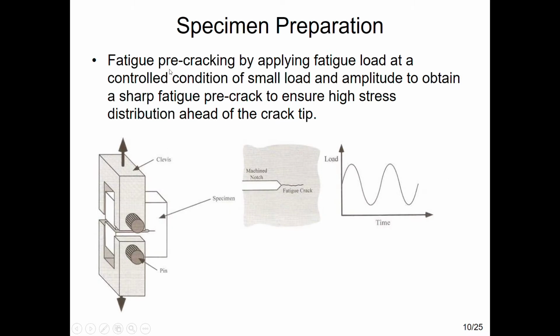Okay, still under the specimen preparation, fatigue pre-cracking by applying fatigue load at a controlled condition of small load amplitude to obtain a sharp fatigue pre-crack to ensure high stress distribution ahead of the crack tip. This is if you want to assess in terms of the fatigue loading. Let's say I put a specimen where this is the cross-sectional area.